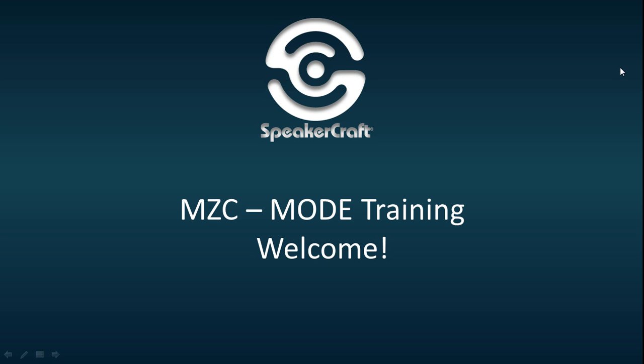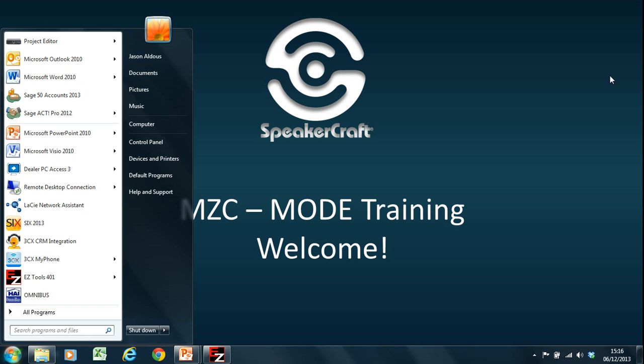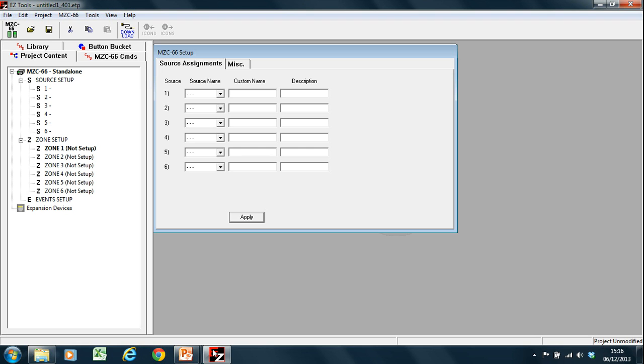In this particular course we're going to be looking at programming our zones on the MZC multi-zone controller. In the previous videos we've given you an overview. We've also looked at easy tools. We had a look at how to assign your sources, how to collate and test your commands, and now we're going to be looking at how to use those commands in a zone, and particularly how to program keypads within a zone. So far we've been working from a template.